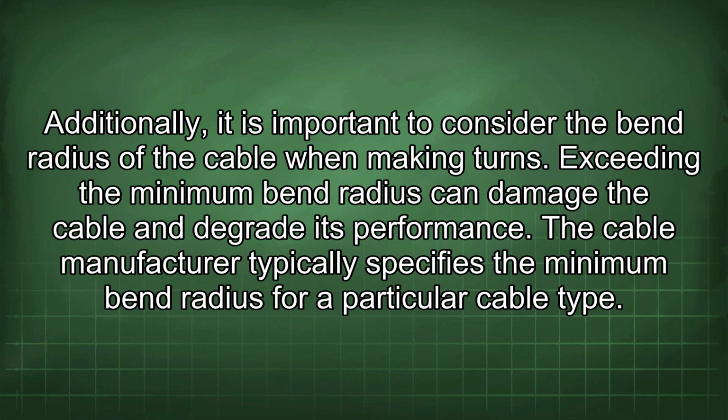Additionally, it is important to consider the bend radius of the cable when making turns. Exceeding the minimum bend radius can damage the cable and degrade its performance. The cable manufacturer typically specifies the minimum bend radius for a particular cable type.